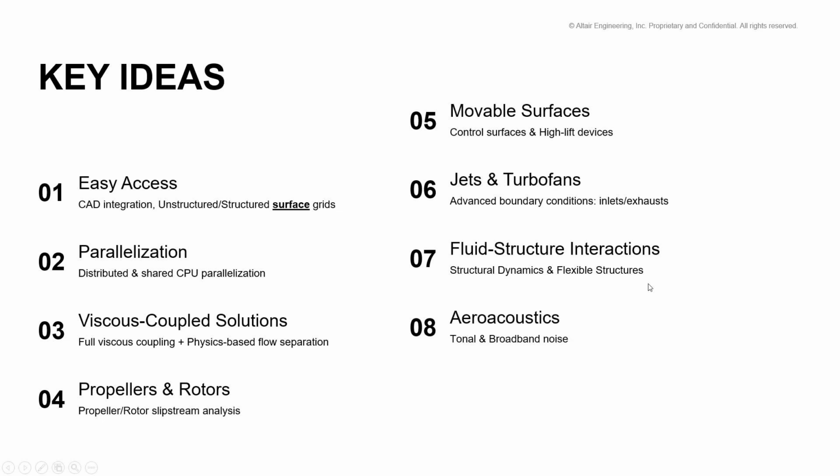So aeroacoustics: the acoustics part was integrated into the tool from the NASA Glenn Center acoustic tools for tonal and broadband noises, primarily restricted to open rotors or ducted fans as of now. For example, it could not be applied to the noise coming out of a moving car as of now. But anything related to open rotors, ducted fans, jets and turbofans, those kinds of acoustics we can capture, and this goes to NASA Glenn Center, from where the acoustic tools were integrated into FlightStream.